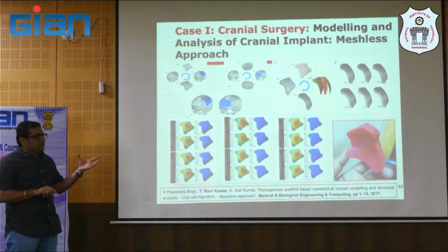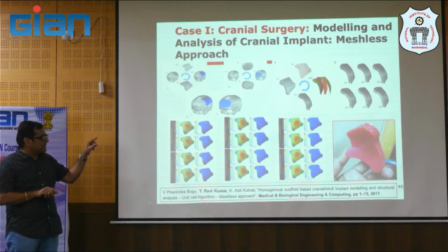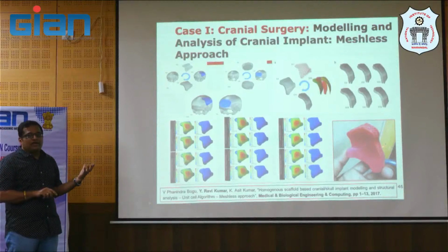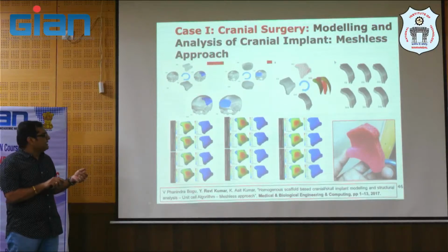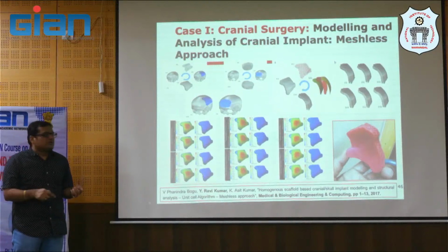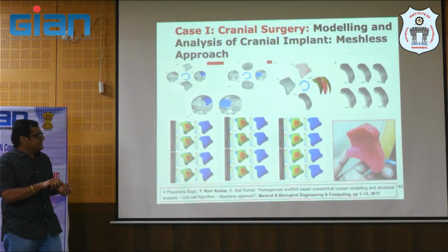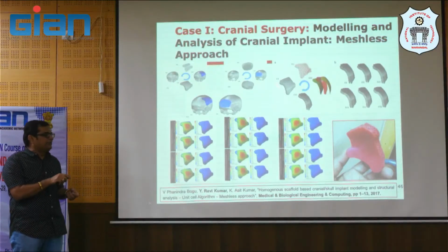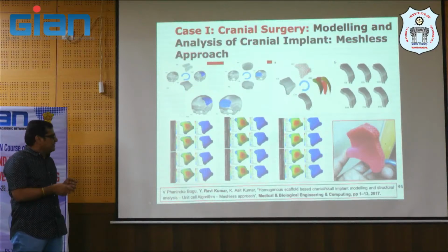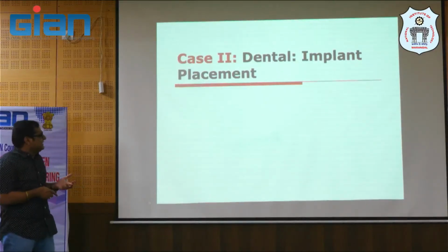And finally, you design and fabricate, but here you see it is a kind of sandwich structure, your skull, right? So you have the inner thickness of the skull around 0.8, 0.9, and the outer is 0.4, 0.5, and in between you have a porous structure. So there is no other way than 3D printing to make it in a single setup, right? It is impossible otherwise, right? And it is patient specific. So you can very well adjust this porosity as per the patient requirement, the personalized implant which you can design, right?